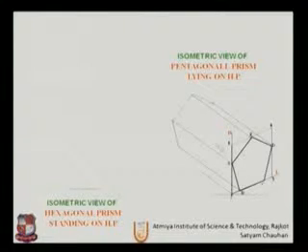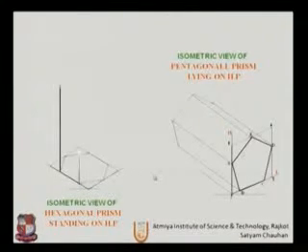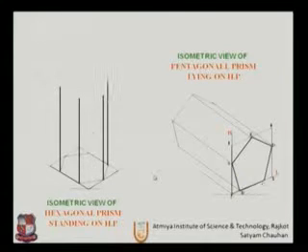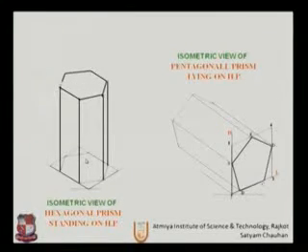So here it will look 3D, and to draw the hexagonal prism, we take the top view of the hexagon as we learned, draw a vertical projection from each point and simply join the lines to give us the hexagonal prism.